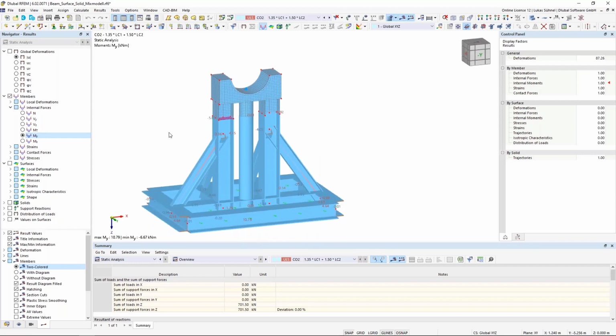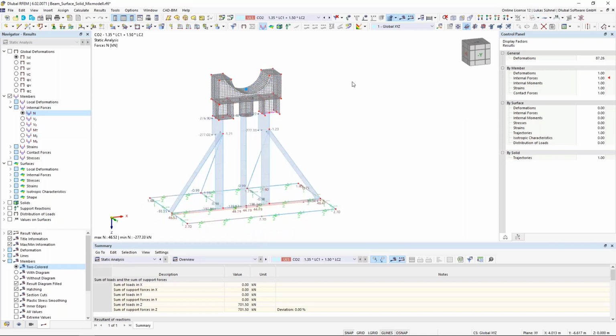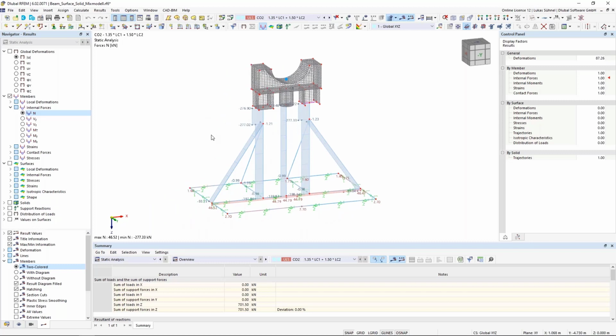What could be an issue is, of course, buckling. But for buckling, I can use some limit checks, some specific checks to judge if buckling is actually an issue. And such a check can be found inside the Eurocode 3 in chapter 6.3.1.2 in brackets (4).